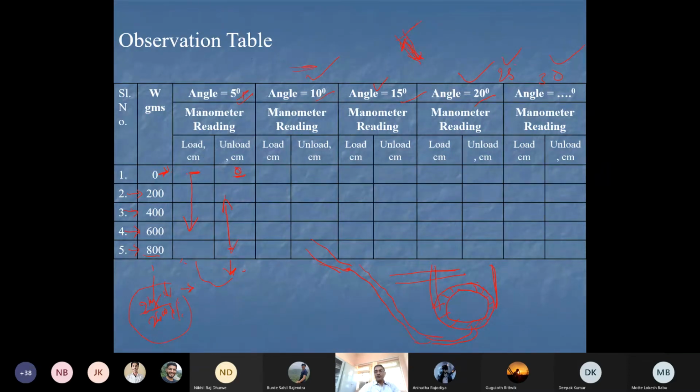Hysteresis you have learned in soil. Any system shows a difference when soil moisture is added and then soil moisture is removed. If you recall, even for the soil moisture characteristic curve, there is one for addition and another for removal. This difference in the same condition, even in soil, is called hysteresis loss of soil moisture.